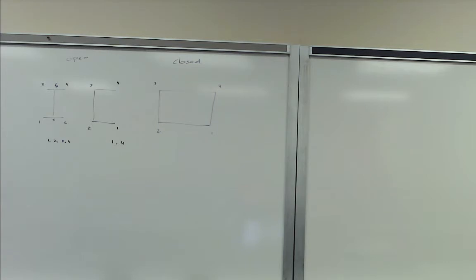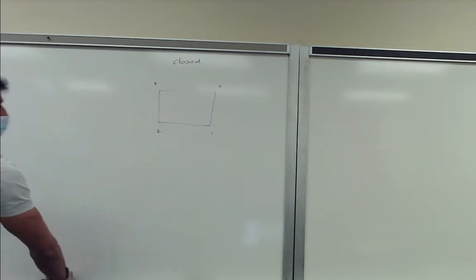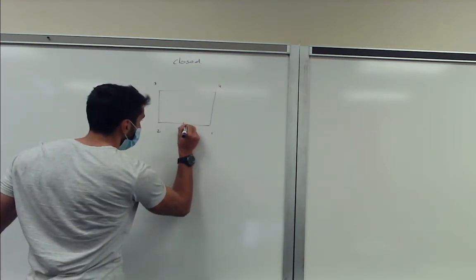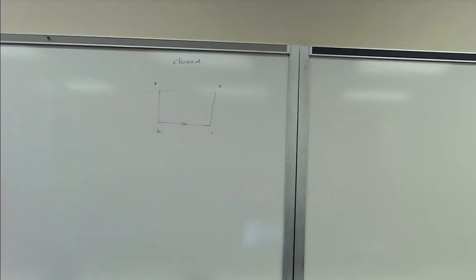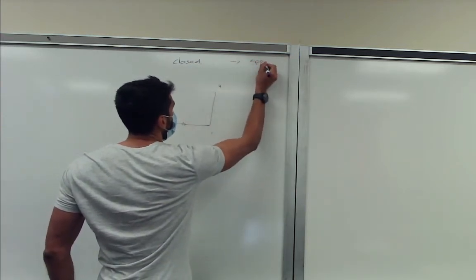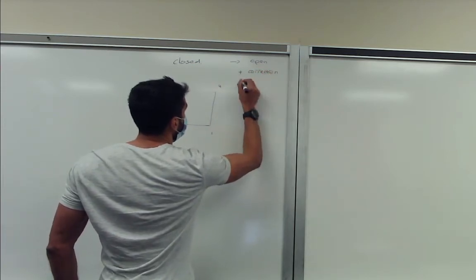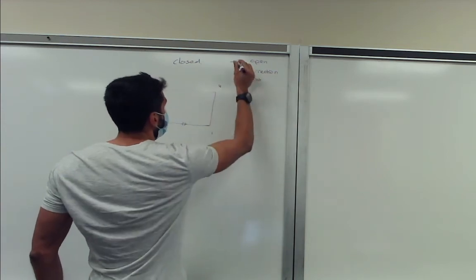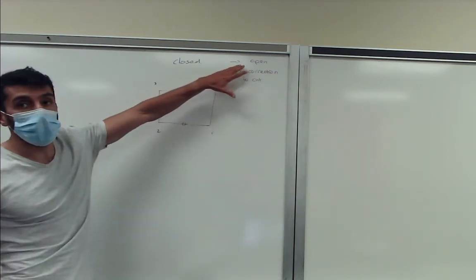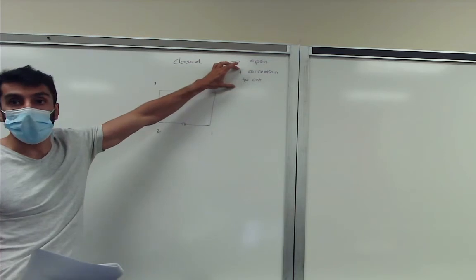Because in this location, since it's closed, we don't know where the starting point is and we cannot assume a 0 starting point. So what we do is we basically cut the structure open. We make a small cut here. And we say the closed structure is actually an open structure plus some correction for the cut we made. So now we can use our open shear flow equations to calculate the open section shear flows, and then we just have to compensate for the cut.